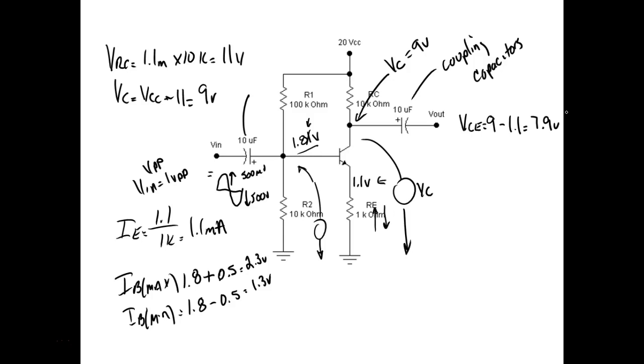Now understand, these guys are not creating power. We call that thing up there, that 20 volts, we call that the power supply. So the power supply is not only having to provide power to the amplifier, it's also trying to give us a power gain from our input to output. So some people have a misconception that a power amplifier creates power. It cannot create power, right? Y'all understand? All it can do is change its form. So the ultimate goal of an amplifier is to get power gain.